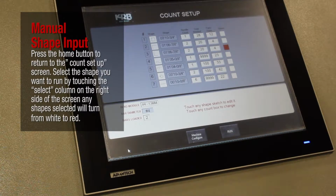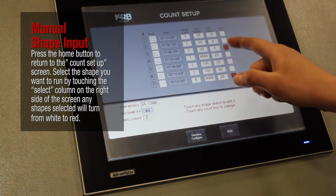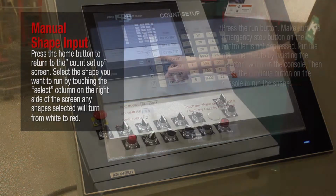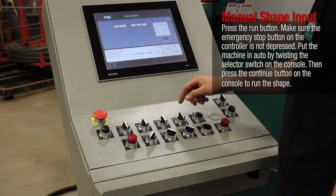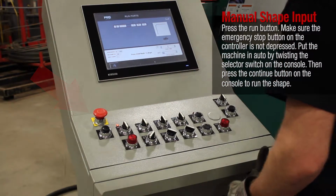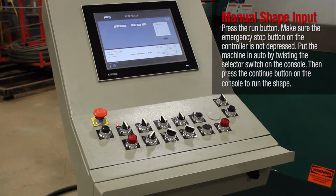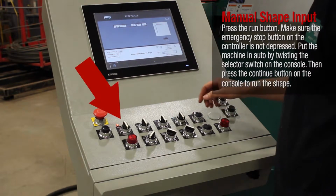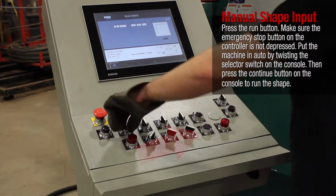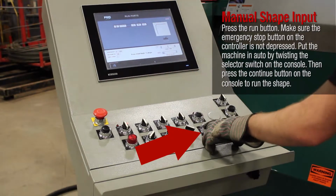Select the shape you want to run by touching the Select column on the right side of the screen. Any shape selected will turn from white to red. Press the Run button. Make sure the emergency stop button on the controller is not depressed. Put the machine in auto by twisting the selector switch of the console. Then, press the Continue button on the console to run the shape.